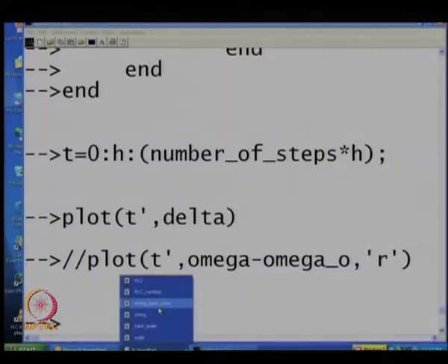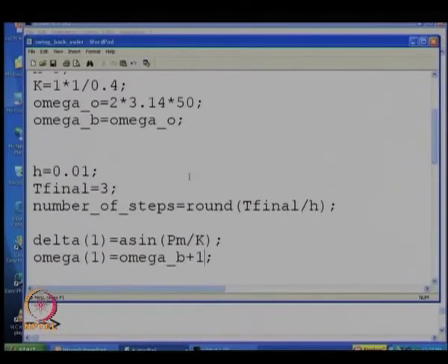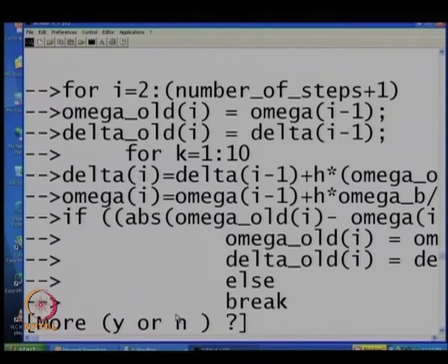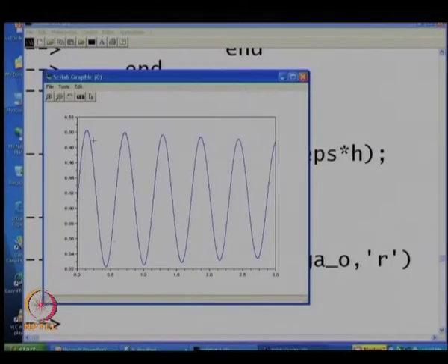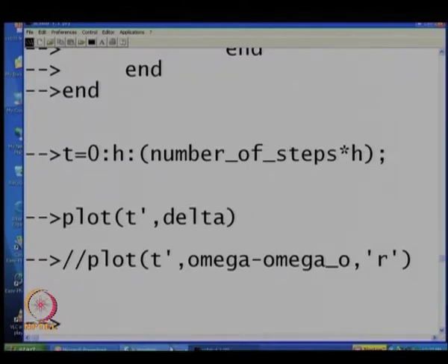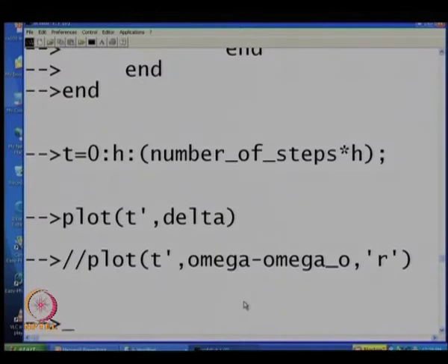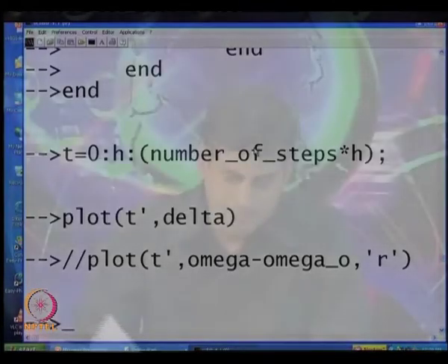Of course, if I use backward Euler method with a very small time step, you are going to get a reasonably accurate solution. So, I just numerically integrate it with a smaller time step. Well, the answer is slightly different, and we are coming closer to the solution we have in mind. So, of course, reducing time step is one of the ways you can get a more accurate solution. So, with this I end my discussion about the numerical integration of swing equations.